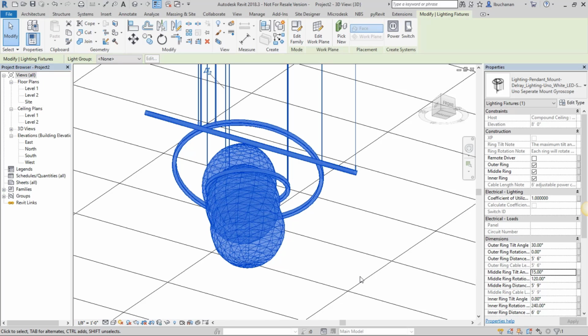What's happening is that there's an IES file attached to this. It's giving you this ball of light that's been given to us by the lighting manufacturer, and it allows us to do sustainability tests, lighting analysis tests, and test how much heat is coming off of this product within your space along with everything else that's in the space. If we didn't have that IES file, we wouldn't be able to run those scenarios to get some photorealistic lighting effects in our space.